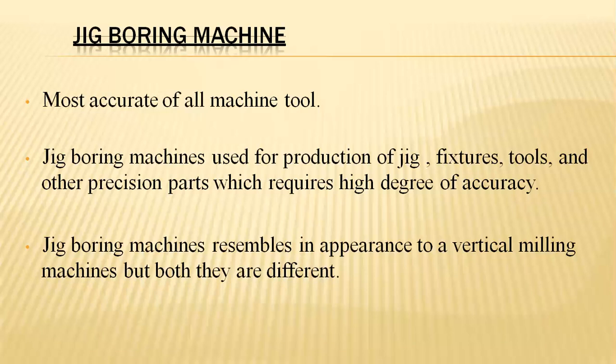You need to get good precision-oriented dimensions in the opposite parts, and to operate over the work parts, tools need to be utilized. So those tools are developed in this jig boring machine because of its accuracy in machining. Compared to almost all the machineries, this jig boring machine has the affinity of getting better accuracy.